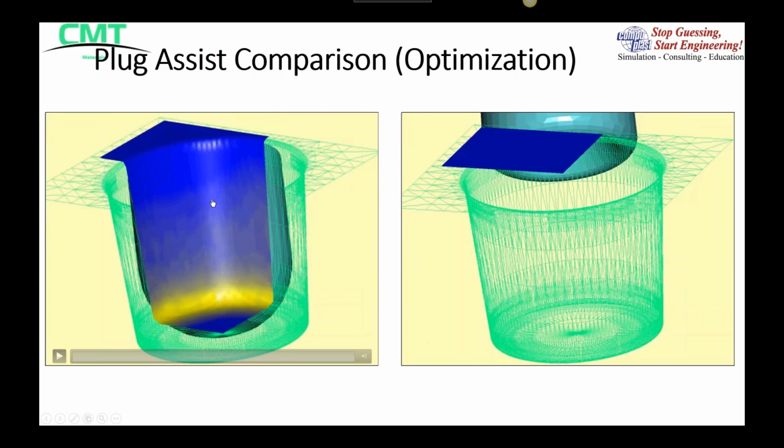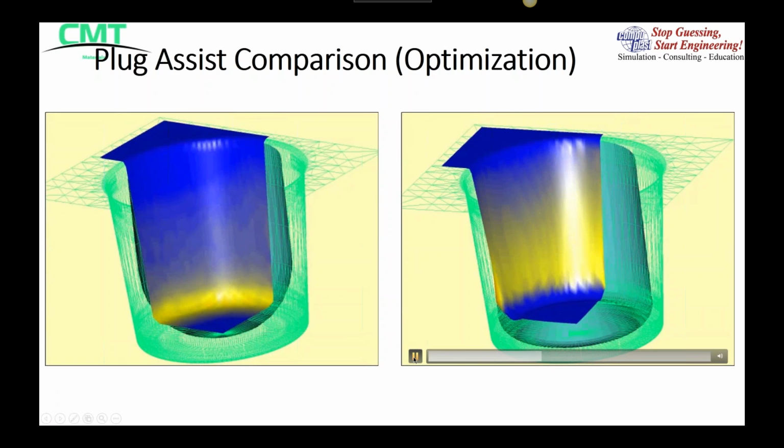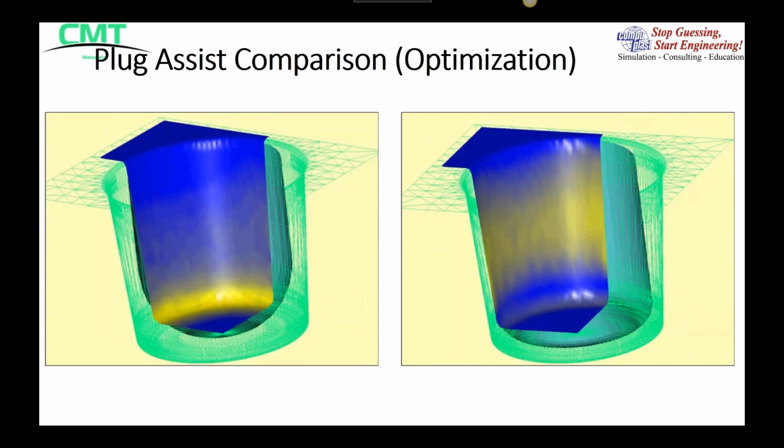Now we keep the same scale, and we use a different plug, which is a slightly larger diameter, and it's a concave bottom. You can see here at the bottom of this plug is concave. And we go down to the same distance, and then we pull the vacuum, and now we see a very different thickness distribution. In other words, the thinnest part is actually the vertical wall, and the bottom corner is a little bit thicker, and certainly thicker than what it is on this side.